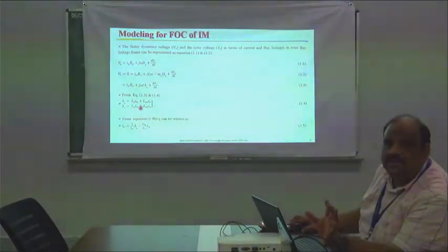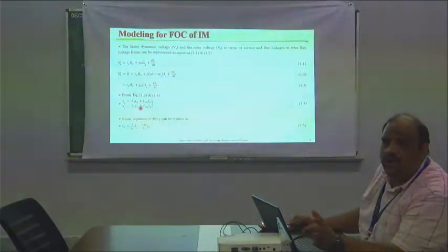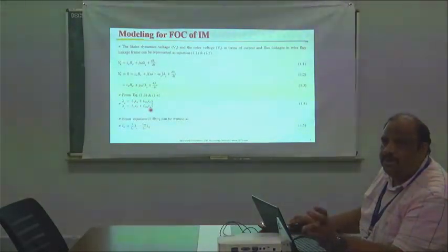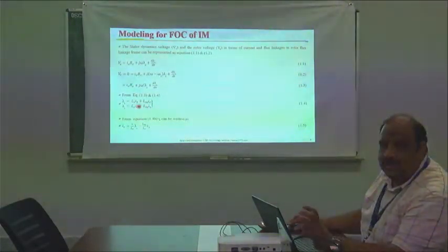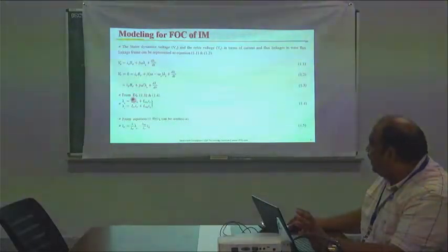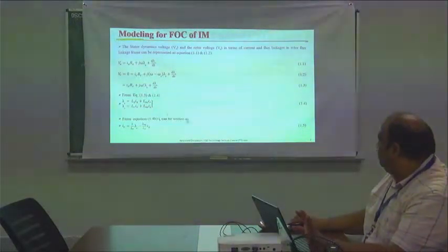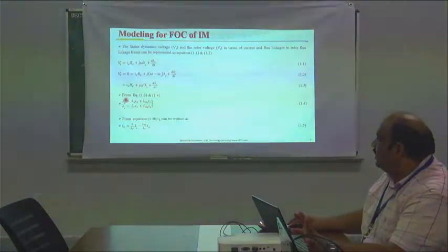So we'll call the self-inductance, in my nomenclature, LLR, and the mutual inductance will be LM, and together Ls is equal to LLR plus LM. So you will have the mutual inductance of the self-coil and the mutual inductance of the cross-coil. This is how you get the equation with respect to the inductance.